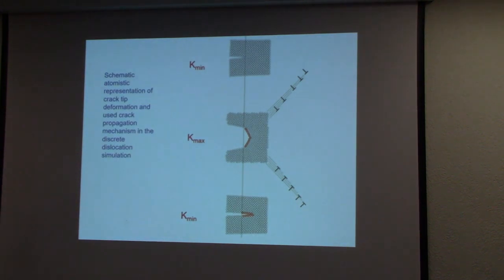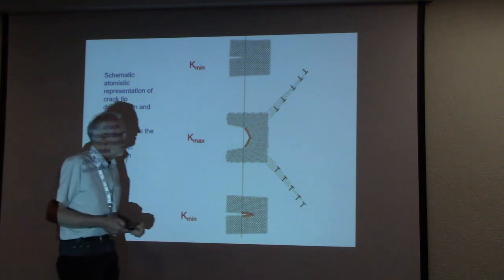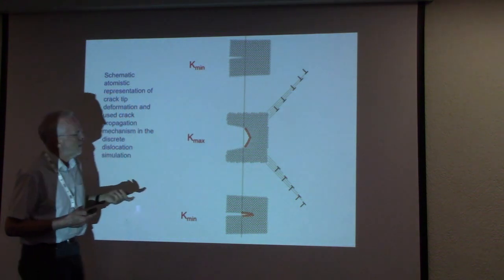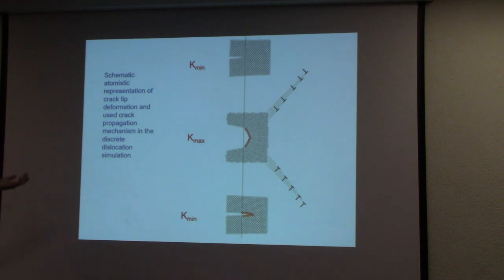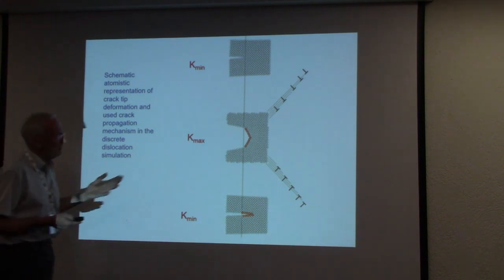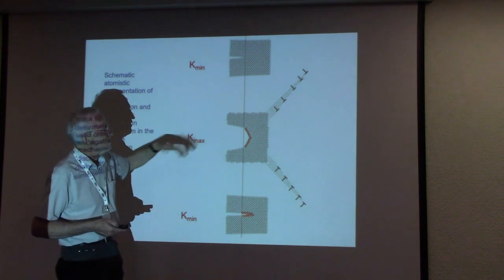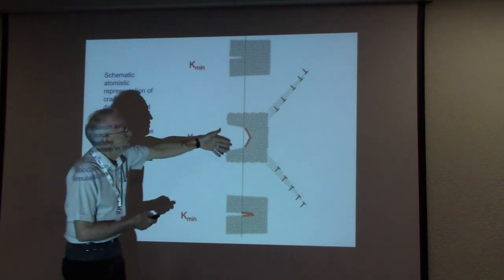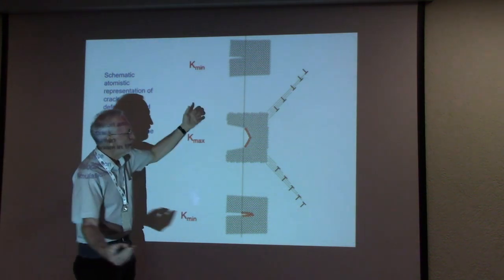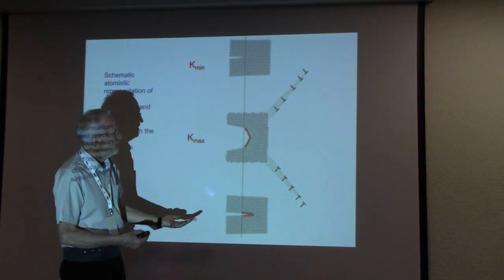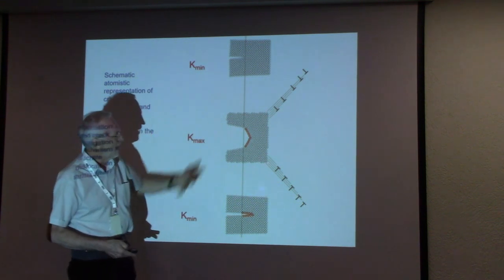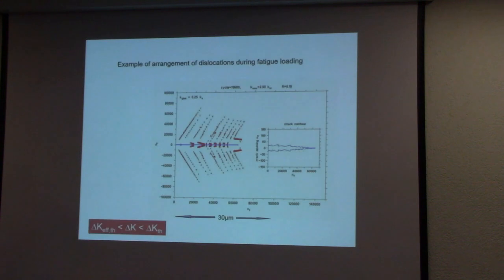What we have done in the 90s is to understand the threshold for fatigue crack propagation by this discrete nature, because at these very low load amplitudes, the number of dislocations is quite low, so that classical continuum mechanics cannot be applied. What we have done is simply, okay, we load up, generate dislocations. If we unload, few dislocations will roll back, and they form new area, and in the next loading cycle, the same will happen. That's really the process in ductile materials.